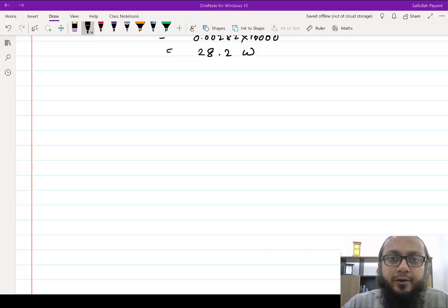In the problem we have taken now, the machine or transmission line impedances were given, and then we converted them into the per unit system, into per unit quantities, by defining one base value of the power and the voltage. Now, generally, if you see the nameplate of machines or transformers, they will give you the per unit quantities instead of the actual values.